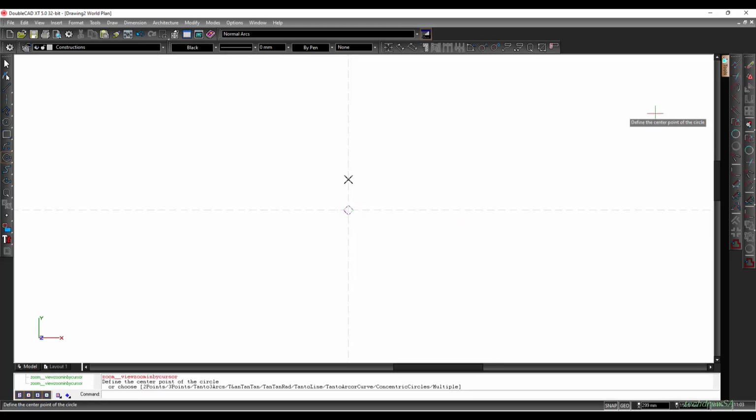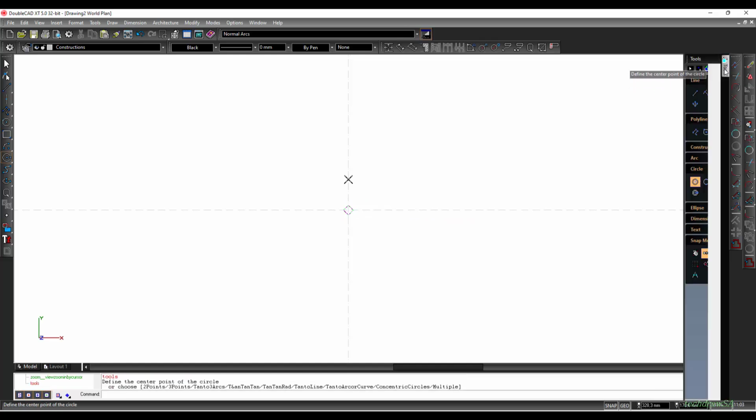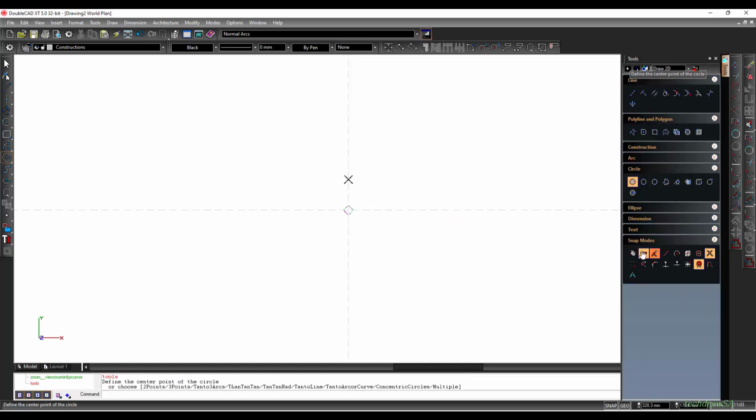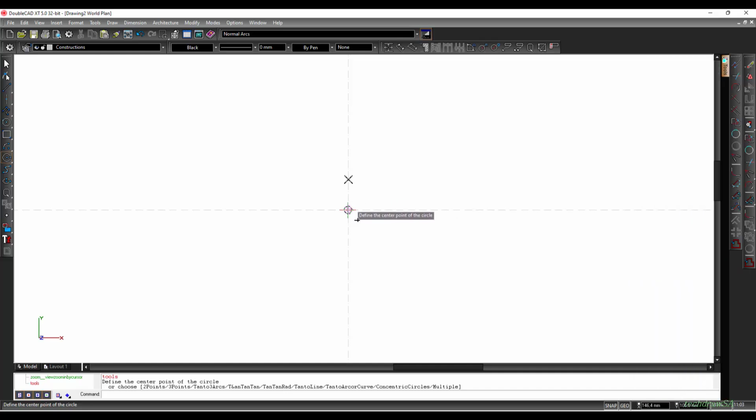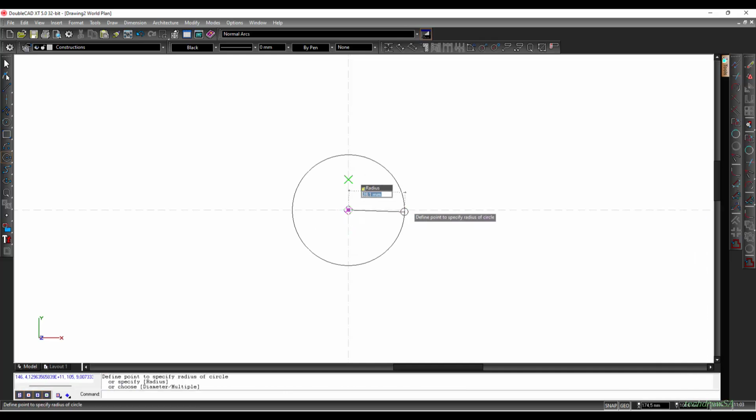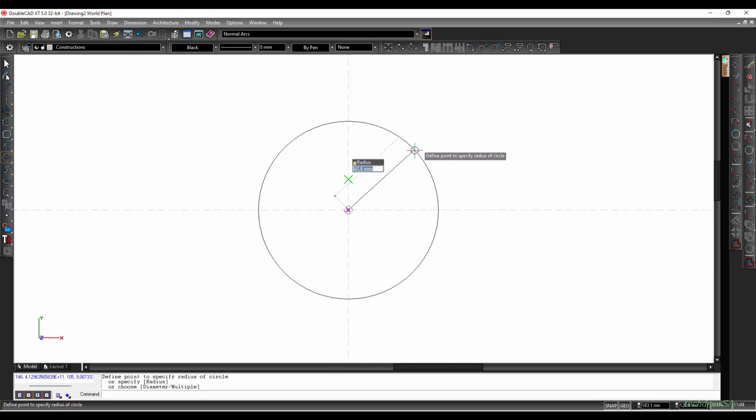If this doesn't happen, like we said in the first lesson, just go to the tools and make sure that these 4 selections have been turned on. So that's the endpoint or vertex, that is your middle point, and that is the intersection. And then this show magnetic point is very important because that's that little pink diamond that you see when you hover over an intersection.